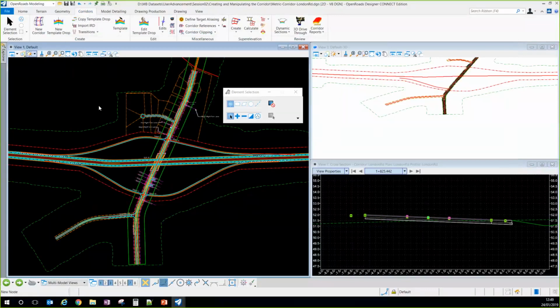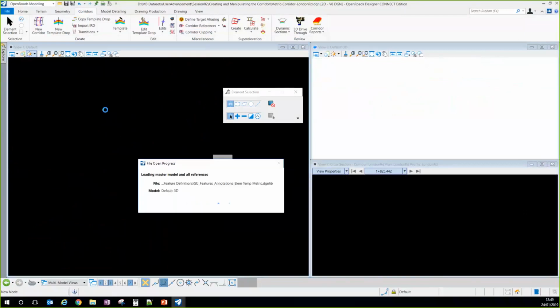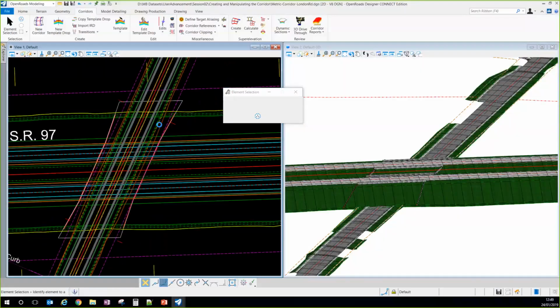So in the other file we have a corridor with divided highway running above our project, and so a bridge is necessary at this intersection, and we need to adjust this corridor to integrate the bridge. So with the corridor clipping tool, we just need to draw a shape around your bridge area, so for instance, this shape, and use it as a clipping reference. And all the corridor elements inside will be trimmed.